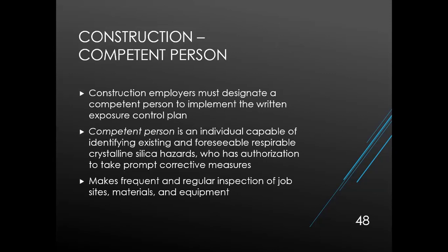For construction, the employers must designate a competent person to implement the written exposure control plan. This is a person capable of identifying existing and foreseeable respirable crystalline silica hazards, who has authorization to take prompt corrective measures and makes frequent and regular inspections of job sites, materials, and equipment being used.